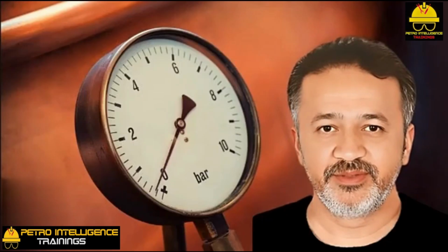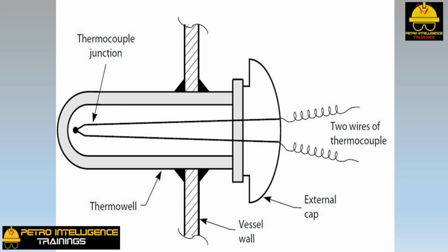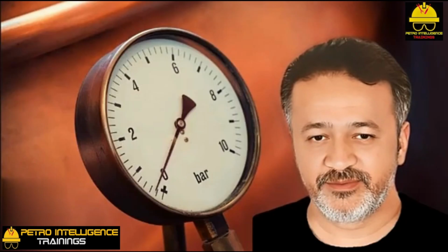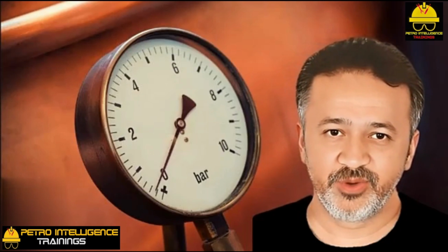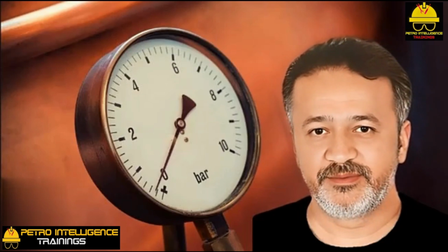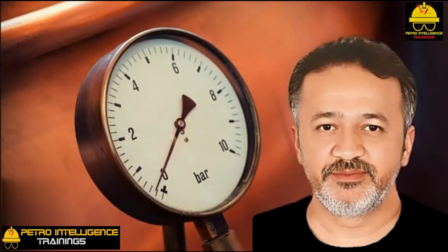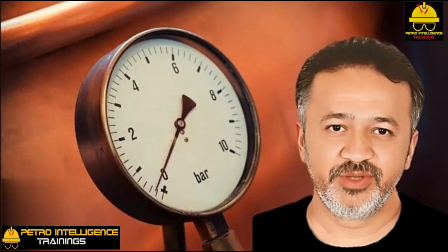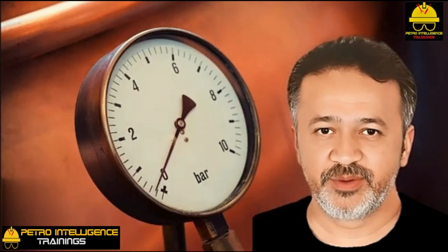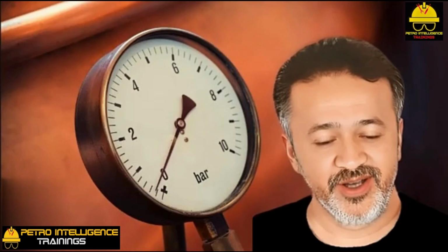Safety note. This picture is somewhat misleading. It implies that most thermowells are welded in place. Typically, thermowells are screwed into a 1-inch nozzle in the vessel wall. I talked in the preceding section about unscrewing a thermocouple. This is perfectly safe. The same comment applies to extracting a screwed-in dial thermometer from a thermowell. However, sometimes less experienced people have made a deadly error in unscrewing a thermowell instead of a thermocouple. Unscrewing a thermowell opens up the process fluid directly to the atmosphere.